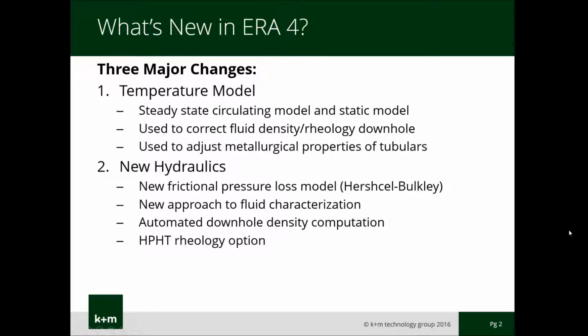ERA also features a new hydraulic engine, which incorporates the Herschel-Bulkley, otherwise known as yield power law, fluid model. In order to compute downhole fluid behavior, ERA now includes characterization of the fluid composition, which is defined by the oil, water, and solid phases of our fluids. ERA now automatically calculates downhole fluid density based on temperature, pressure, and fluid composition. Downhole fluid rheology can also be automatically computed using one of our preloaded HPHT matrices or by entering custom HPHT test data.